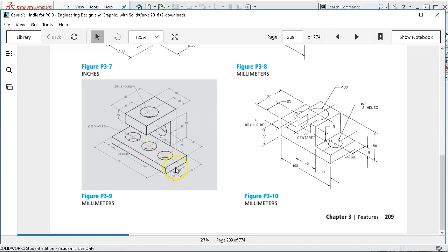So 3.7, probably just the base, adding in the tab. It'd be nice to have this on the mid plane, so like the right plane passes through the center of the part, so that we can extrude both directions. Let's see, this one has just the steps. And the general assumption, I guess the general standard, is that if there's not a depth callout, then the hole is assumed to be through. Right, so basically after we cut the holes, then we can do the little notch shape.